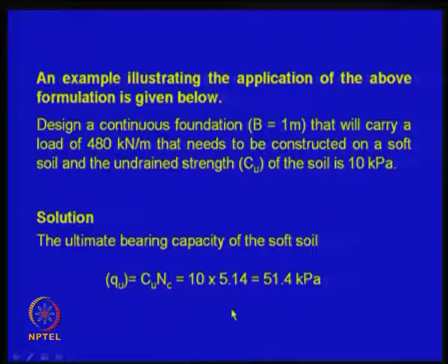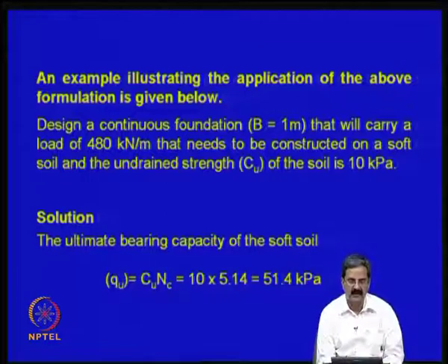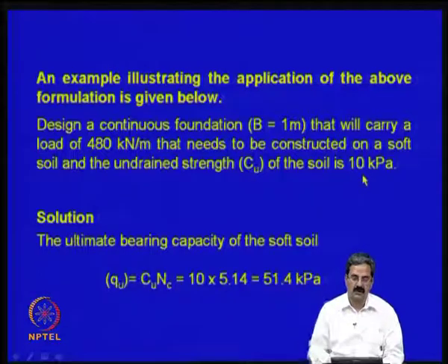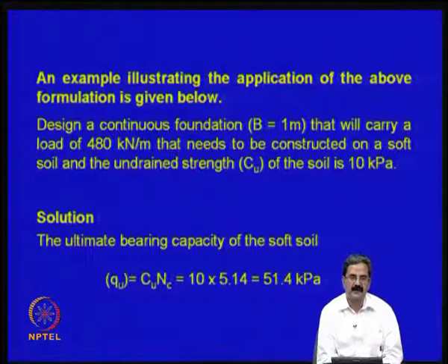I would like to take up a simple problem here, a similar case to what I discussed, where you have sand in one case, but you also have clay nearby, but the load is the same. How do you do that? The bearing capacity improvement we need is 480. We have to see whether it can come. The underlying shear strength of the soil is 10 kPa. So, essentially, even we can solve this type of problem using the soil reinforcement technique, and we will take up this in the next class. Thank you.